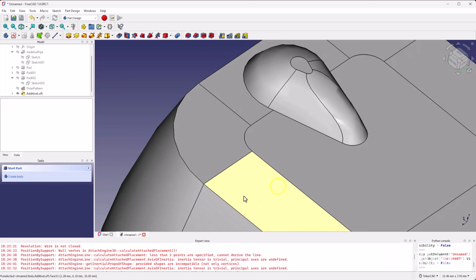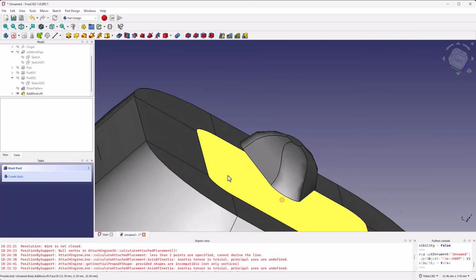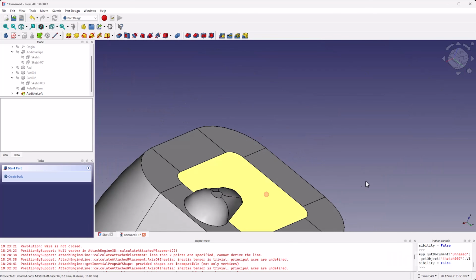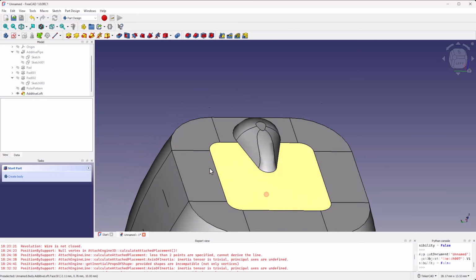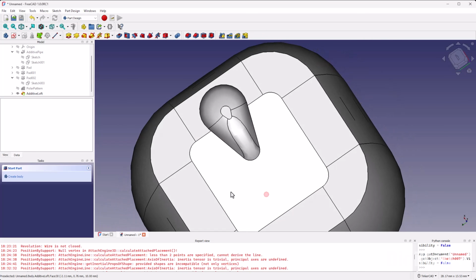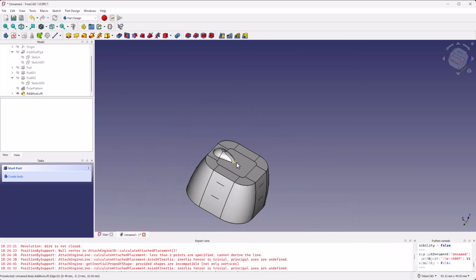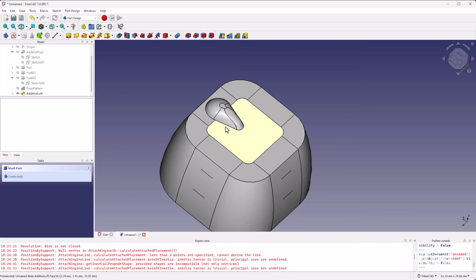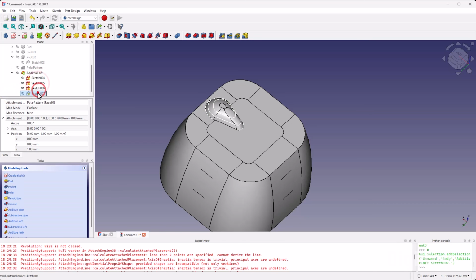And we've got this nice little bump that is our teardrop, and that looks actually pretty good. And this is how you start getting into curved surfaces for making more organic shapes. And there's lots of ways to do this. This is probably the easiest way to do it, even if it's a manual process of defining your cross sections at every point. Make sure these sketches are hidden. In fact, I'll show them. You can actually see how it interpolated among these sketches.